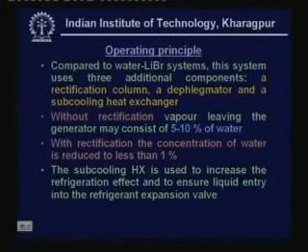Okay, and what is the function of the subcooling heat exchanger? The subcooling heat exchanger is used to increase the refrigeration effect and also to ensure that only liquid enters into the refrigerant expansion valve. Now, let me explain the operating principle.